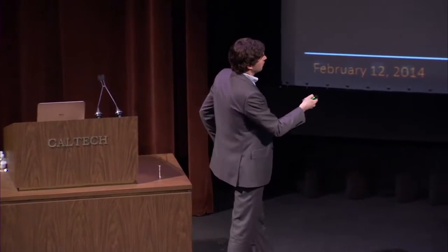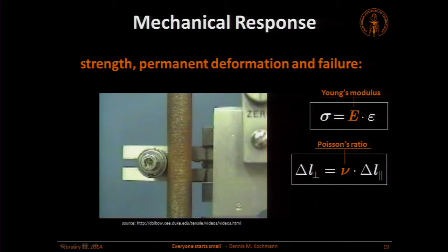And as a matter of fact, if you take the test specimen and you keep pulling to very large loads, what's going to happen is what you see here. First, nothing really happens because the force is increasing very slowly. But at some point, we can see a deformation occurring, and it's going to thin out here. This is what we call necking. The specimen gets thinner and thinner, yet we keep increasing the force. And so what happens is the inevitable.